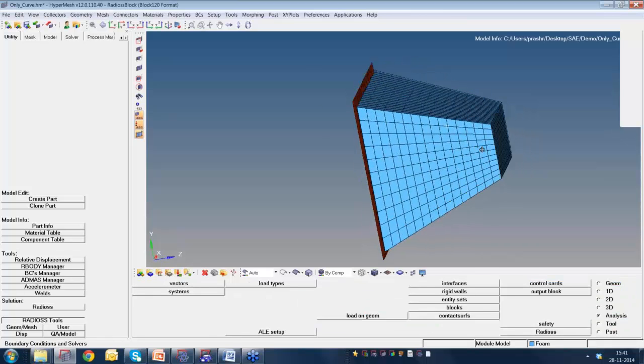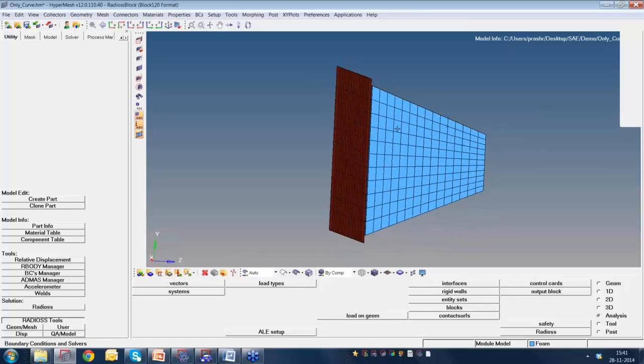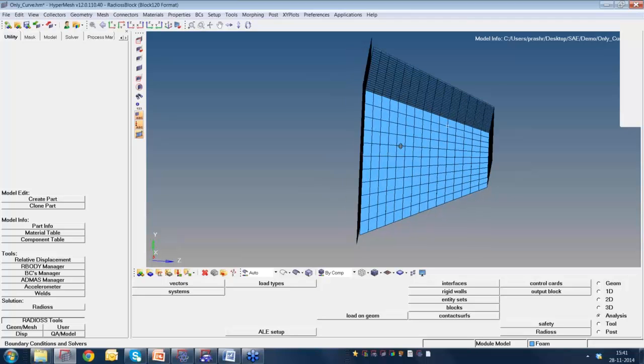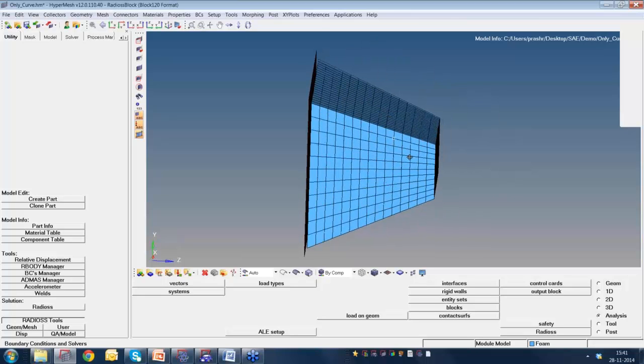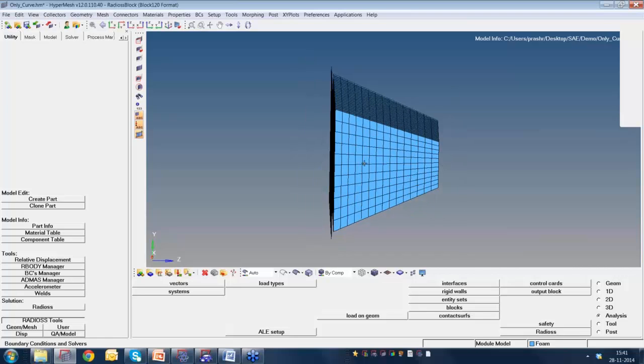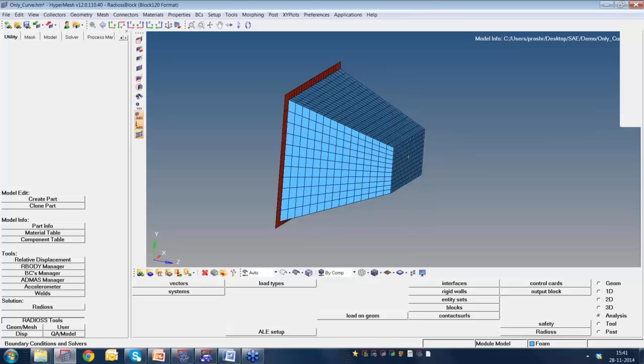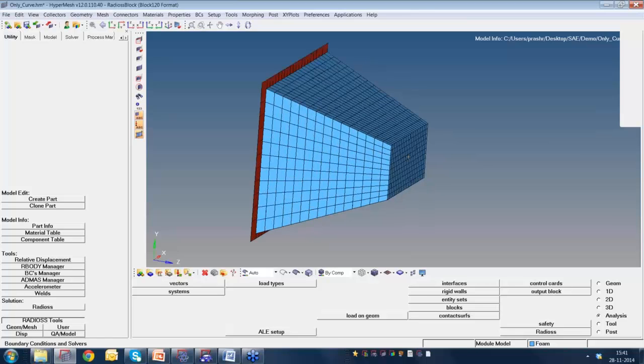Okay. So now one activity is over, wherein you have tied these two. Now you require the rigid impactor. As the regulation says, this should travel and hit against a non-deforming, non-yielding wall. You have to create that. In Radioss terminology, we call that a rigid wall. So you can create a rigid wall.